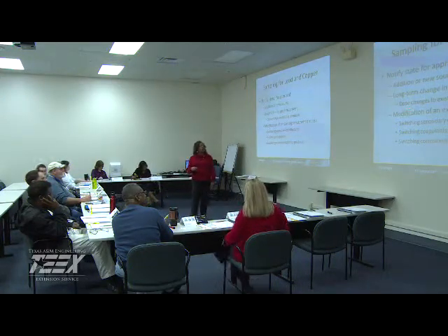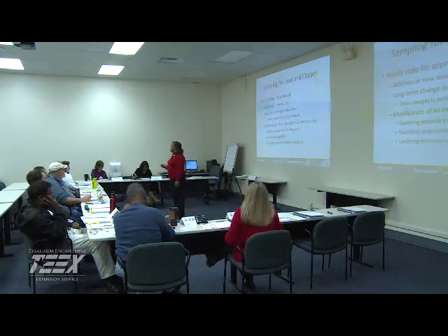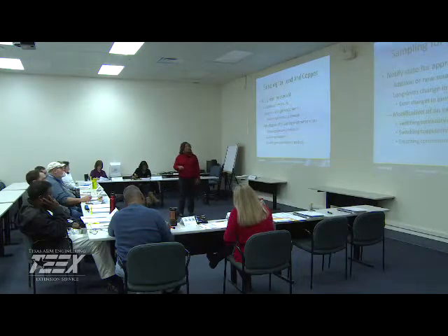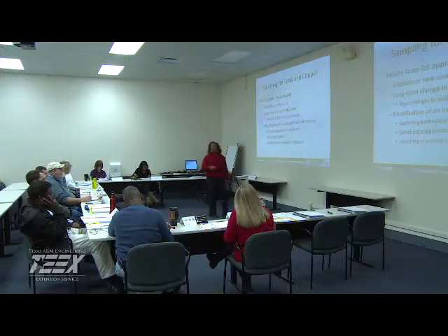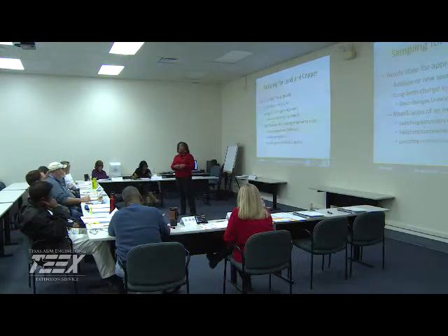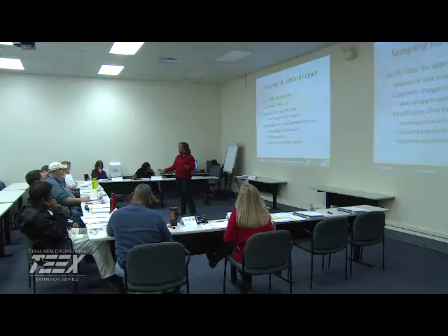Long-term changes in treatment, even just changing the dosage or the chemicals, you need to make sure you're contacting your primacy agency. Modification of existing treatment, you have to notify the state. You can't just go all willy-nilly and do what you want out there. Then they show up for inspection and it's like, oh, I needed to notify you on that. This is giving me better results. No, before you make those modification changes, notify the state.